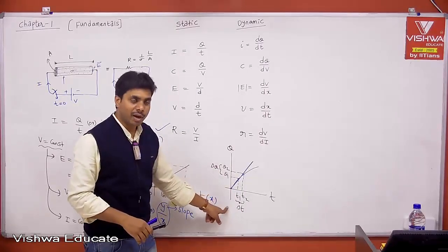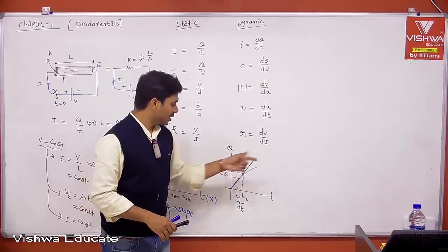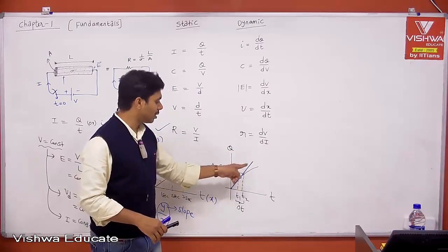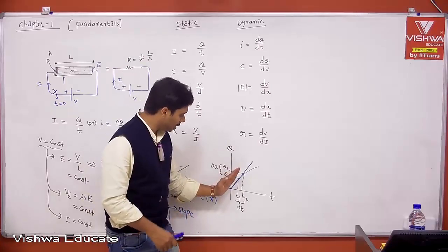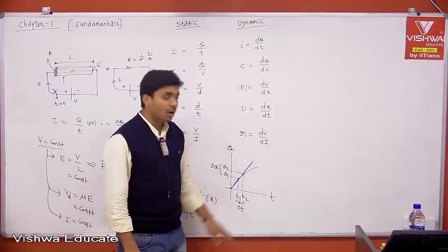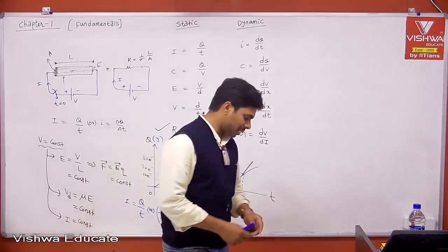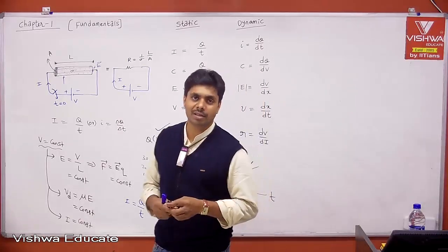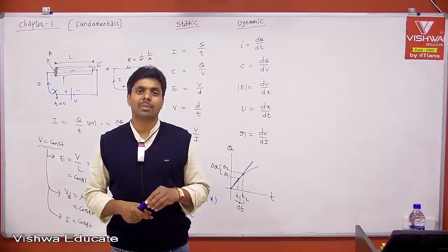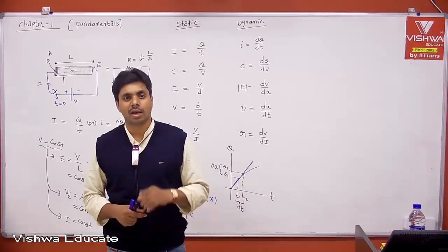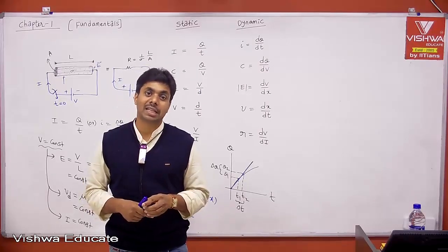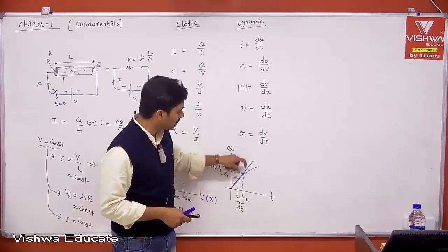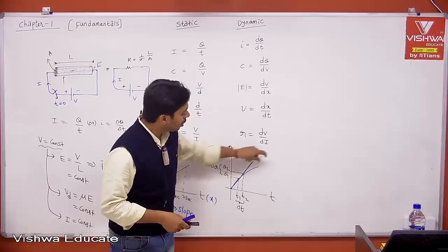The slope of the curve is nothing but the gain, and that depends on the operating point. Because BJT amplifiers and MOSFET amplifiers are all non-linear amplifiers, the gain of the amplifier will depend on the operating point. If the operating point changes, definitely gain changes. At a different point you will have different slopes, because of non-linearity.